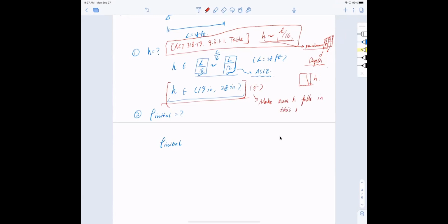So it doesn't have to be exactly 1/16. Actually, that is an estimation when you don't know any information, because this is a first step. Later in the second half of the lecture, we have to calculate the deflection of the beam, where we need to check your h again. And that will actually determine your h more rigorously than just the capacity right now. Okay, clear? Yep. All right, good deal. Thank you for bringing this very good question.